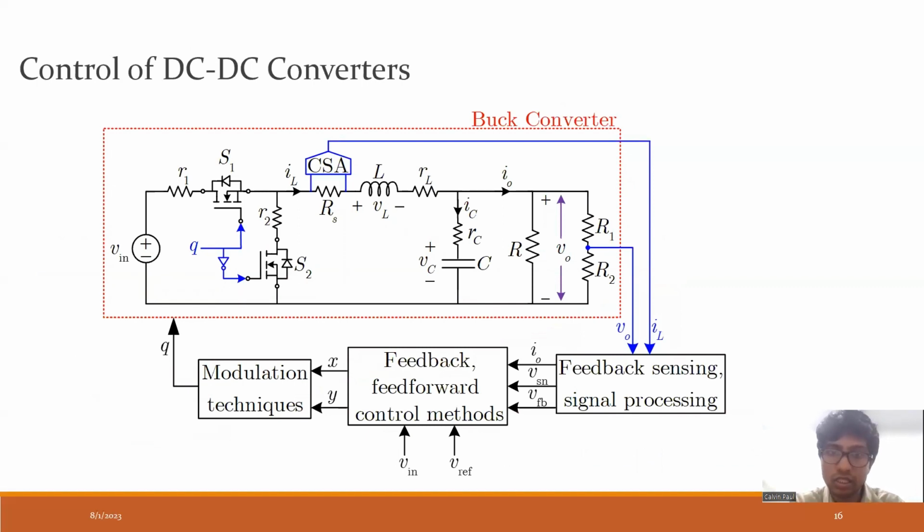So this is the schematic, the circuit of a buck converter. If you observe, this is the main switch, the active switch. This is a complementary switch. So if this is 1, this is high, and this will be off. And if this is 0, this will be 1 and this will be on. So at an instant, both cannot be on. Both should not be on.